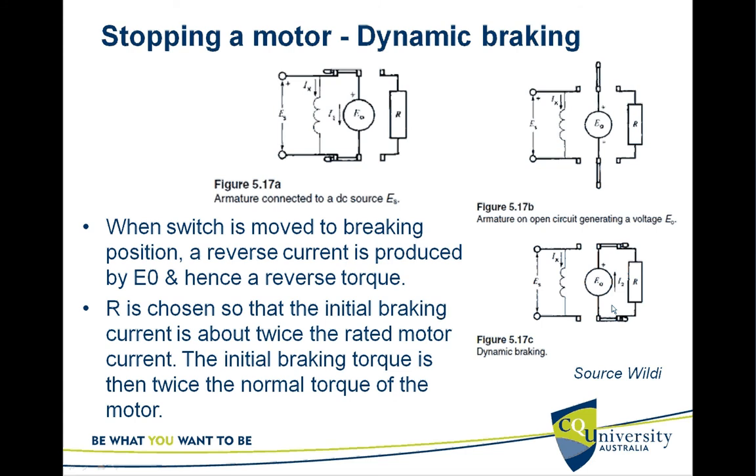You send a higher current in the motor for a shorter period, which is okay because the insulation can withstand that high current, and the system will be decelerated by applying twice the rated torque of the machine.